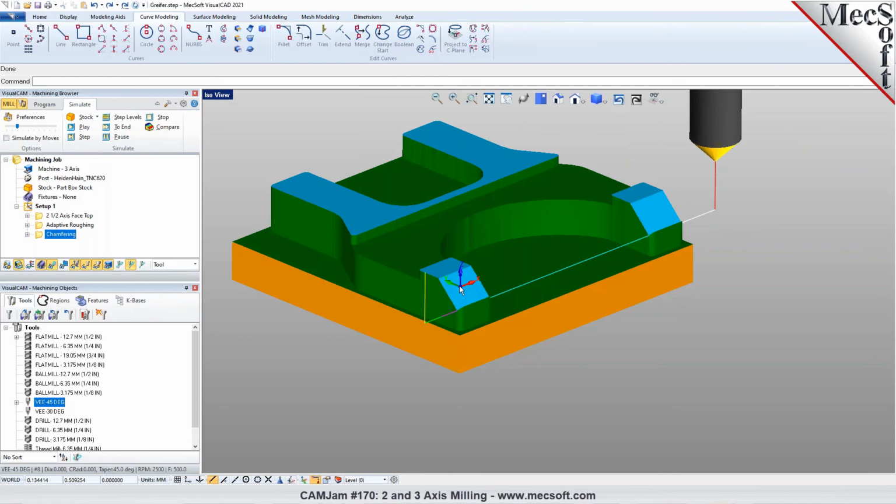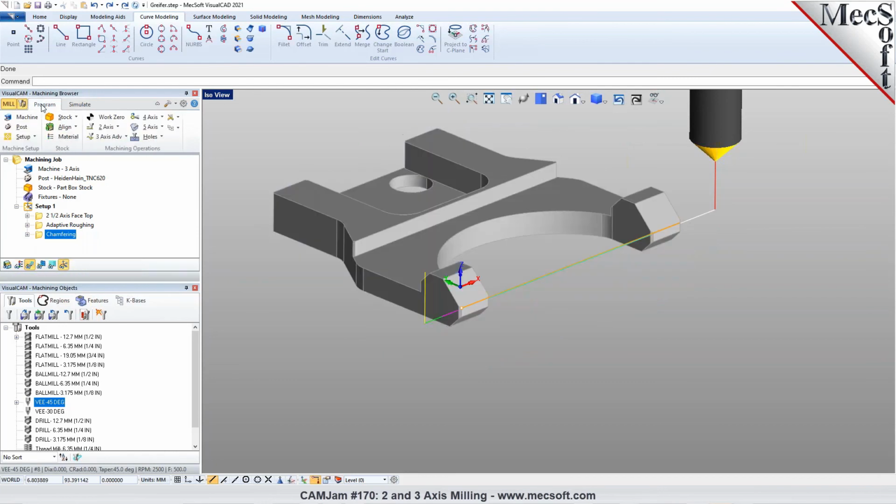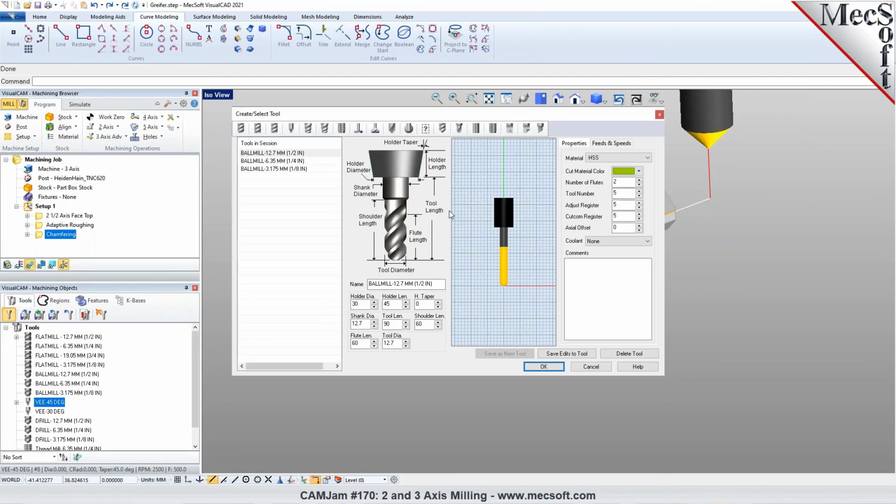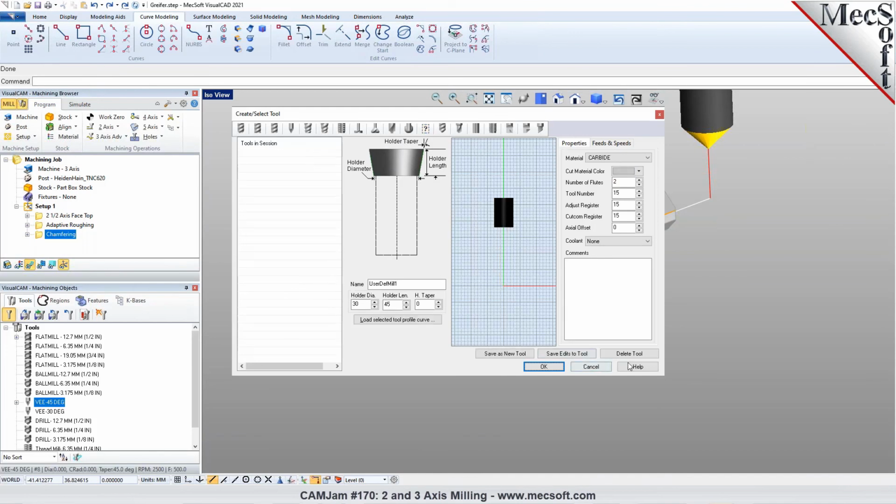Yeah, but I thought about the double-sided chamfering tools. You know them? Normally they got inserts, and you can chamfer from the top and from the bottom. Okay, so what you would have to do is model them as a user-defined tool, and then program it as either a profiling or an engraving. So you will have to model 1/2 of the tool profile, and then you can define it as a user-defined tool, not as a chamfering tool. You can go and define user-defined.